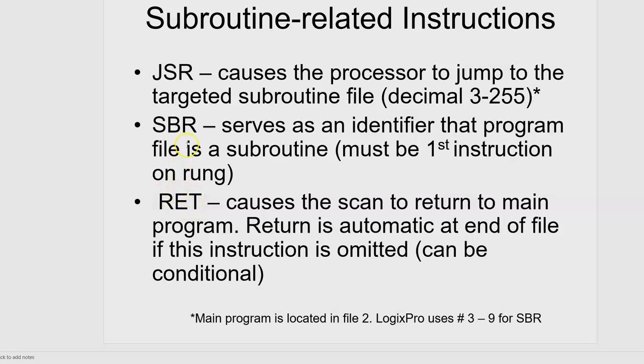And then the return is the instruction to leave the subroutine. If every condition has been met in the subroutine, it will leave the subroutine and then go back, not to the jump to subroutine statement, but to the one that follows it.